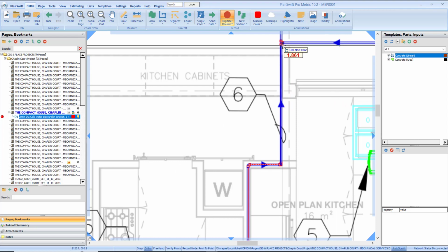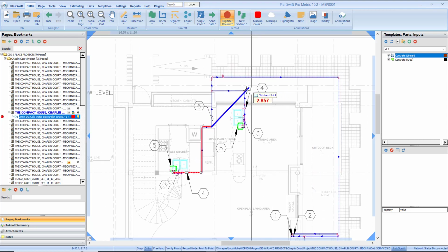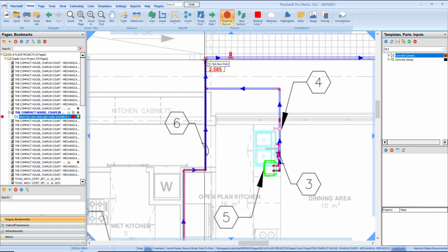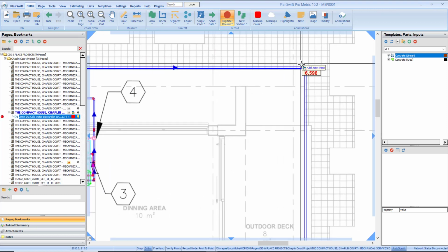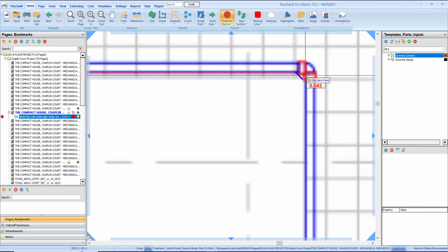All of these you can zoom in to see where these pipes are going. So you're going to measure all the way. At this point I'm measuring as if there is no pipe fitting existing on this particular length of pipe. You can click here. If you really want to get this curve, then you click on your hotkey A and then click on the middle of the arc.